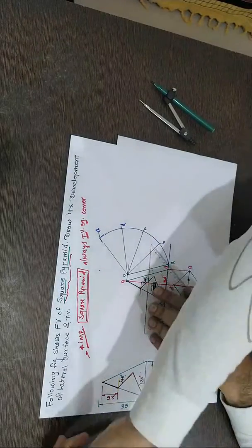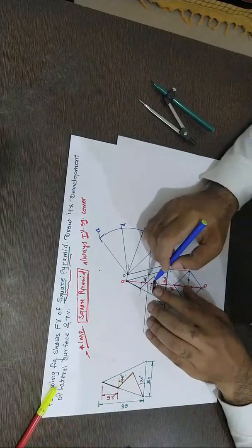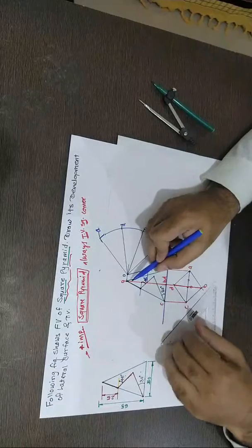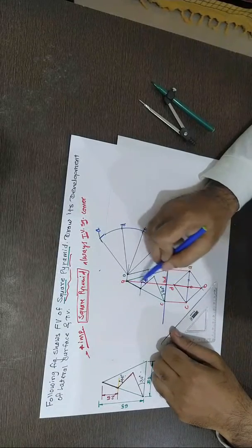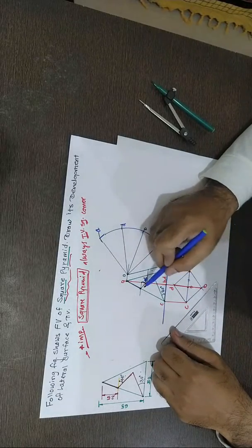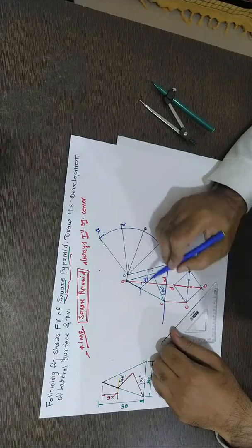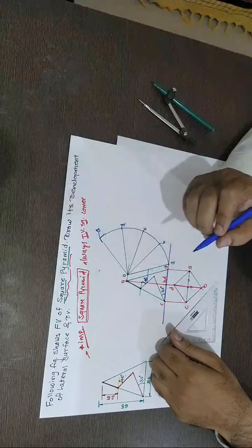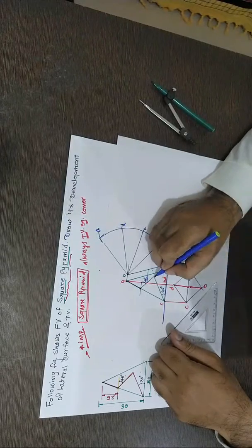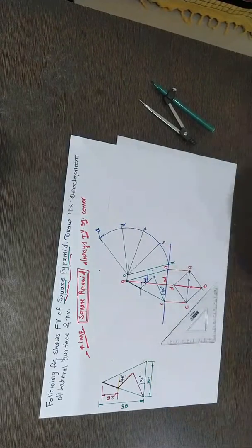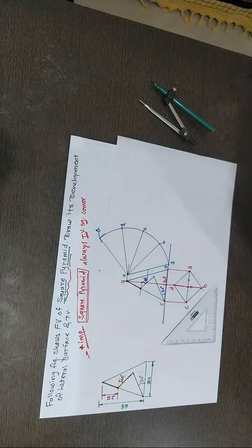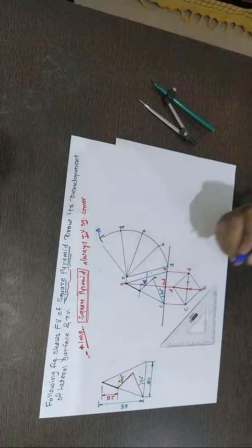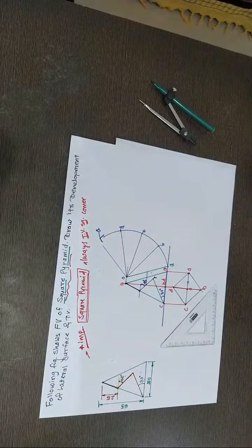So I'm just transferring this intersection point first here. This line is for B and D, 2 slant edges, and this is the intersection. So where should it be projected? Now first, a very important thing: what about this point? I need to mark this as P1, P2 or something for reference. So I'll say P. Right?